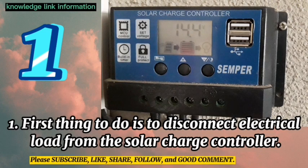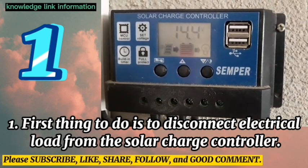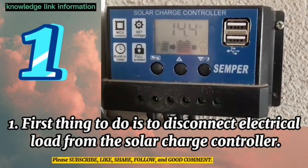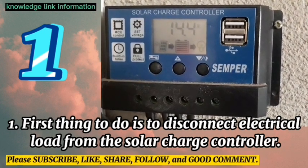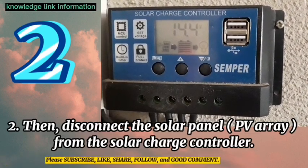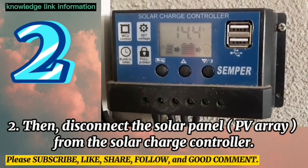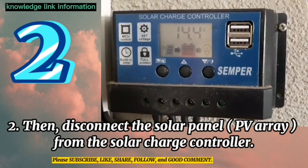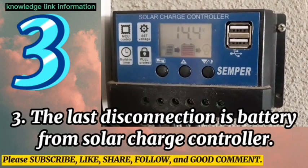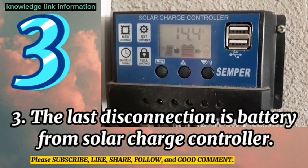Number 1. First thing to do is to disconnect the electrical load from the solar charge controller. Number 2. Then, disconnect the solar panel PV array from the solar charge controller. Number 3. The last disconnection is the battery from the solar charge controller.